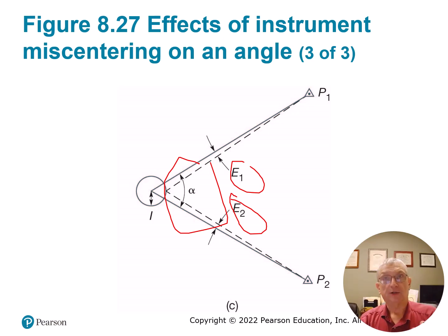I would even challenge you, if you don't believe me, look at a sight out there without touching the instrument, which is the proper way. Don't be touching the tripod, touch the instrument, and then once you've got it, take your hands off the instrument, look at the eyepiece, and then just bump the tripod very easily. You'll see how much error that introduces.